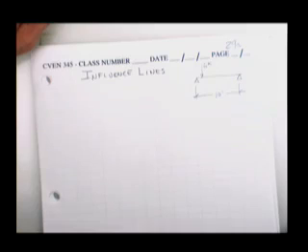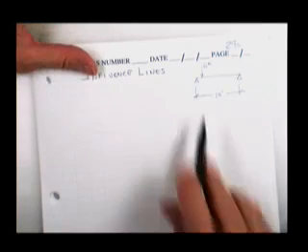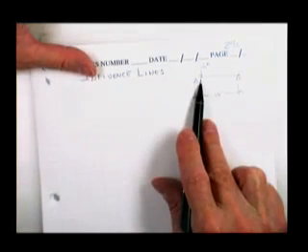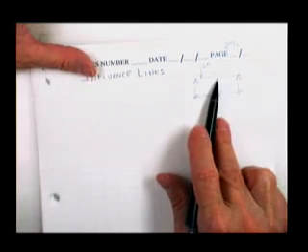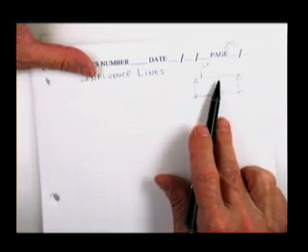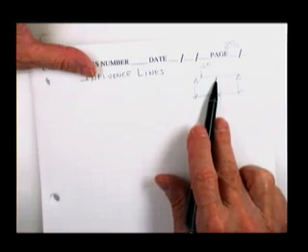Some of them are pretty obvious. Where would you put that load to cause the worst shear in the beam? All right, now you are obviously a moment kind of guy because you are right, putting it in the middle. You've broken things before and you say, look, you don't take a stick like this and put your foot there when you want to break it. You always put your foot in the middle and it breaks a lot easier. The answer to the question of where should you put the load for maximum moment is indeed in the middle.